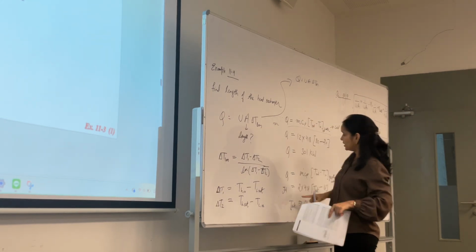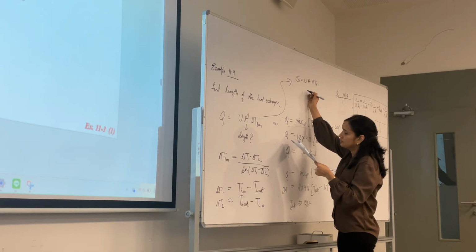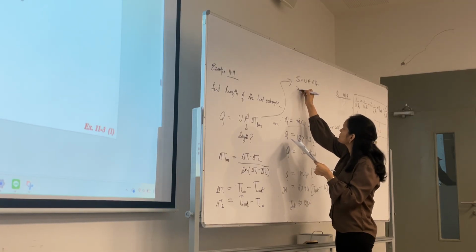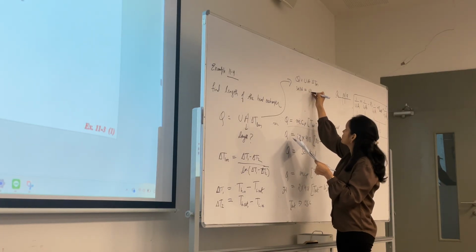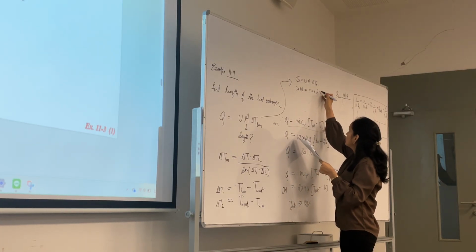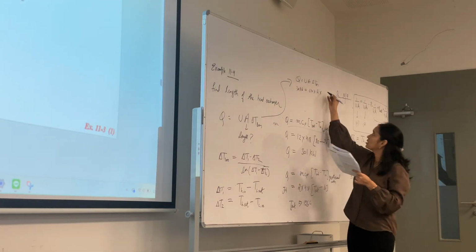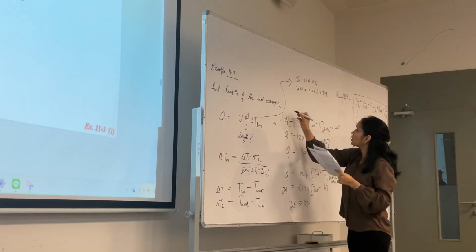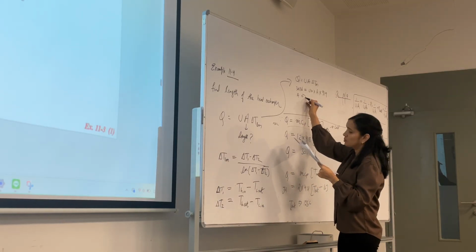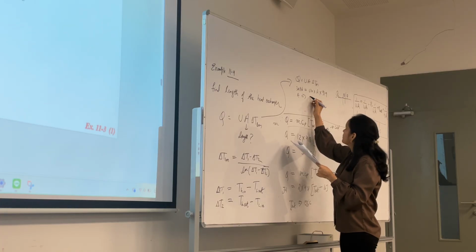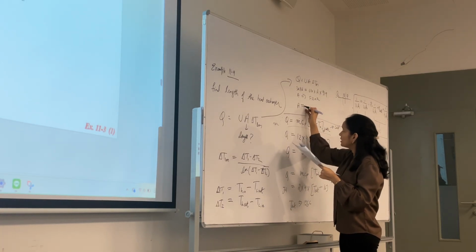Once you have the area, Q we calculated from here, 301 kilowatt. U is given in your question, 640. Area we don't know. Delta TLM we have calculated, 91.9. So I can calculate area from here, which is 5.12 meters square. Now we have the area.